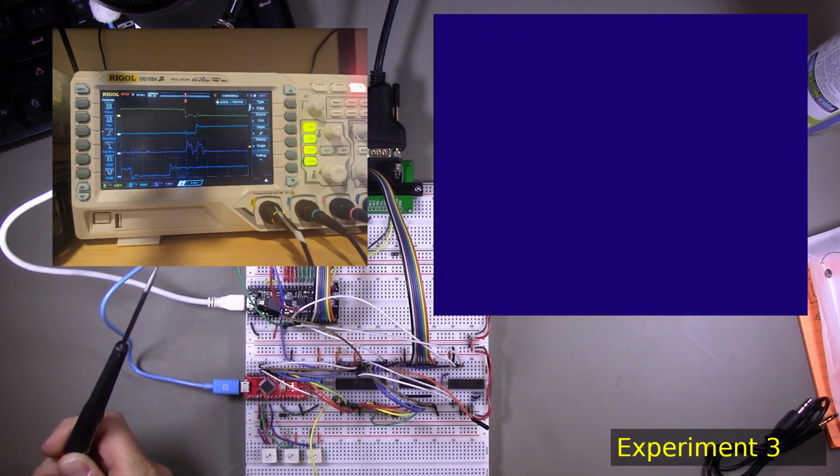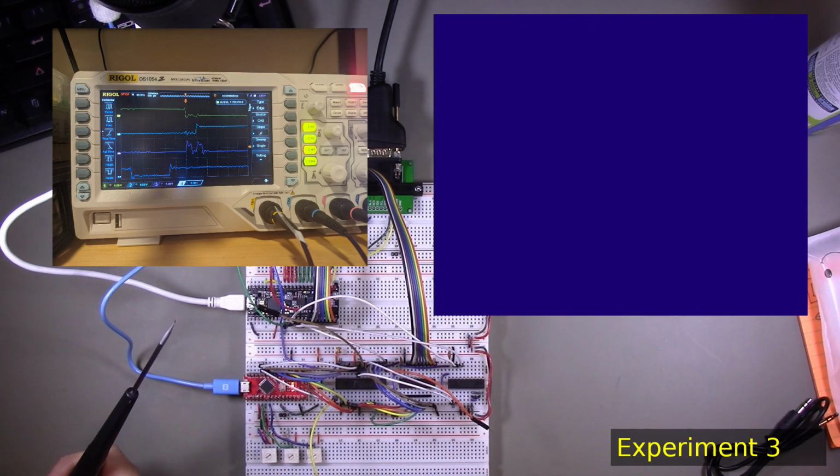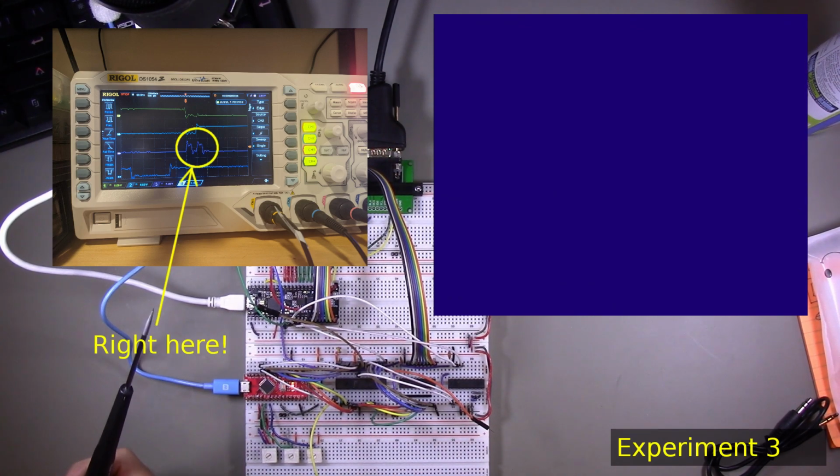So here's a picture of the oscilloscope capture that allowed me to solve the problem. I had one of the probes hooked up to a debug LED that was telling me when the data processing loop thought it had received a byte from that 1 byte FIFO. And of course, what I noticed is that there were 2 pulses in a row for the same byte of data that was sent by the host system.